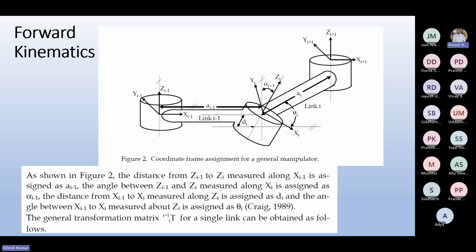Okay. Now, the four parameters, the DH parameters, are in this only. First is a, second is d, third is alpha, fourth is theta. These are the four parameters, DH parameters. Okay. You'll have to remember this: length of link, theta angle, alpha angle, and d. These are the four things, DH parameters. So we'll transform it. What do you mean by transformation? In the DH approach, what happens is we transform.